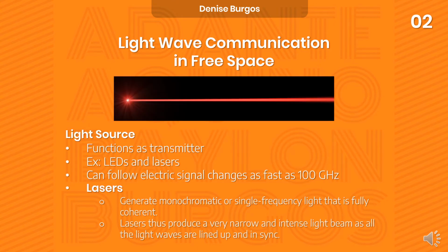The light source functions as the transmitter, for example, LEDs and lasers. It can also follow electrical signals as fast as 100 GHz. The lasers generate monochromatic or single-frequency light that is fully coherent. Lasers thus produce a very narrow and intense light beam, as all the light waves are lined up and in sync.